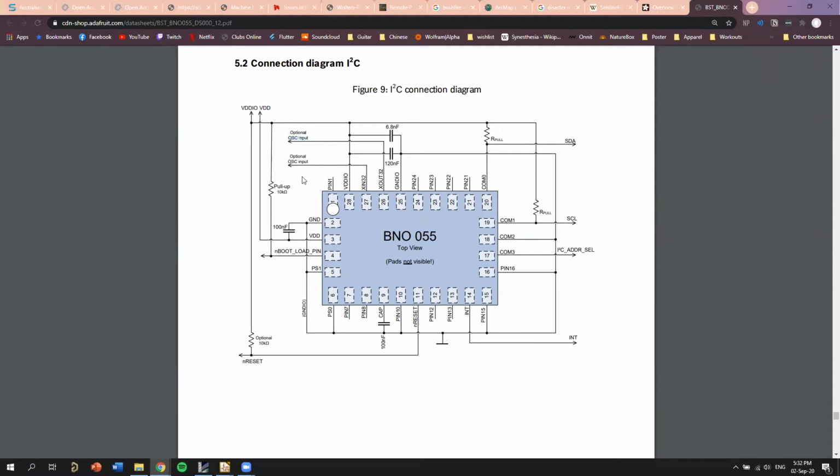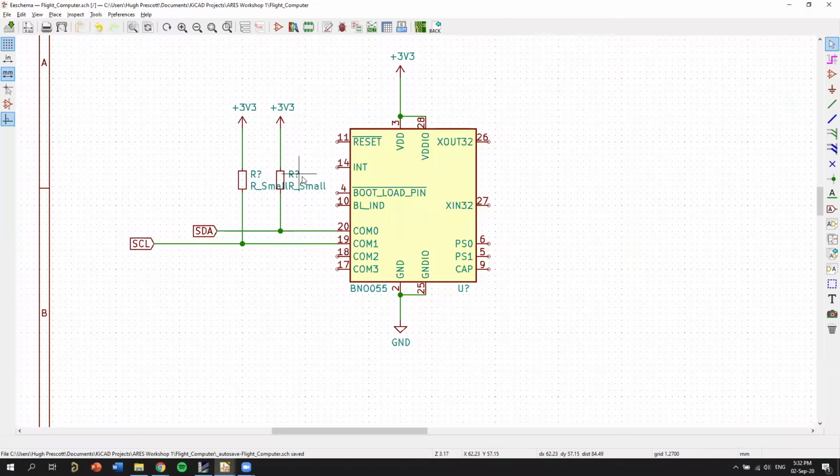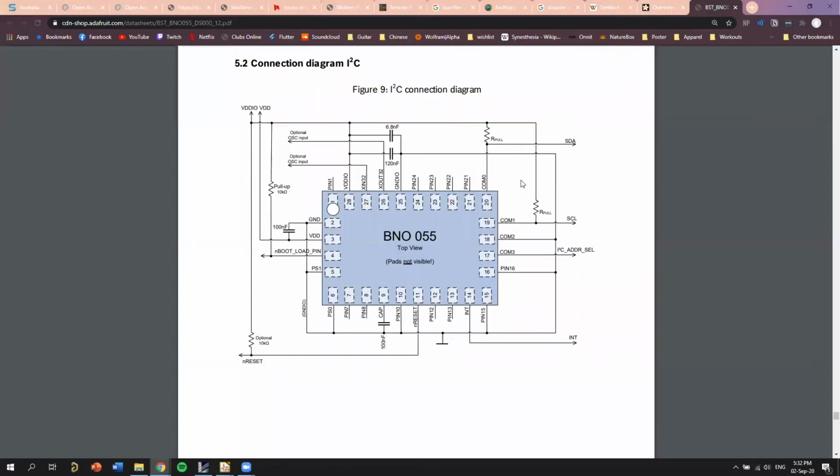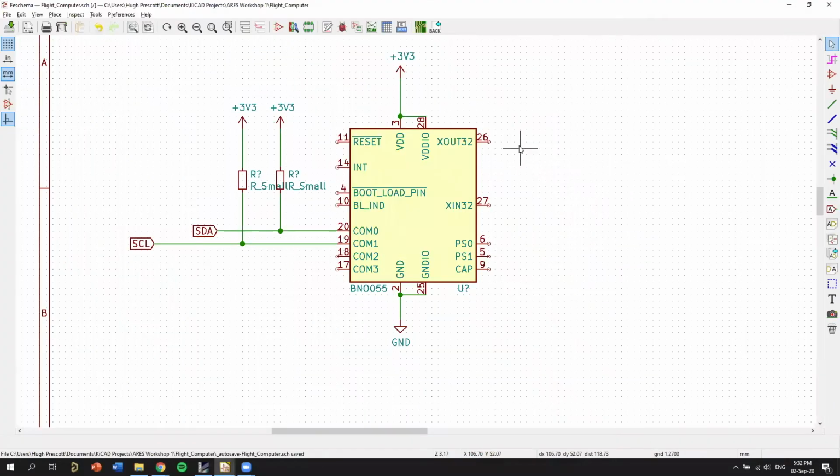So that's basically like your clock speed on a computer. It'll be buzzing away, outputting all the information at a certain rate. You can connect an external oscillator to make it operate faster. I haven't done it before. It's not that complicated, but you just need to be a bit more careful with how you lay out your PCB. But yeah, that's what those weird things are.